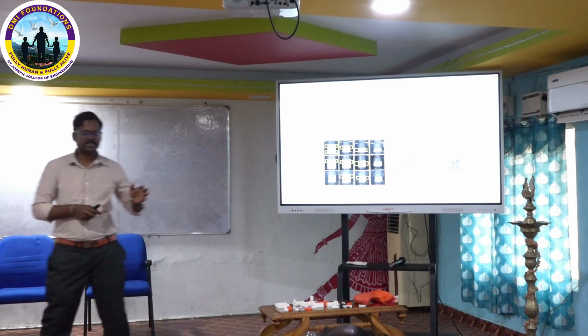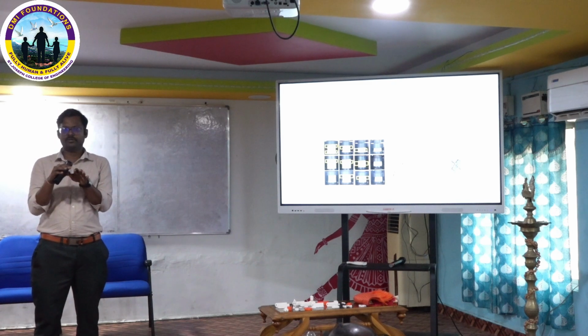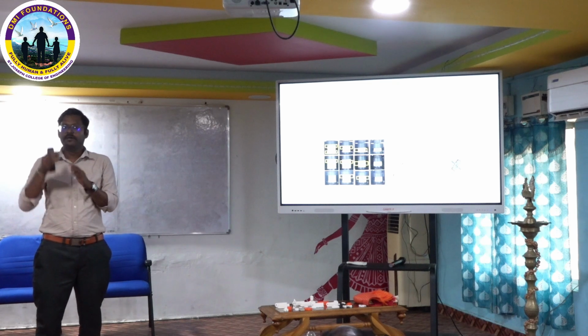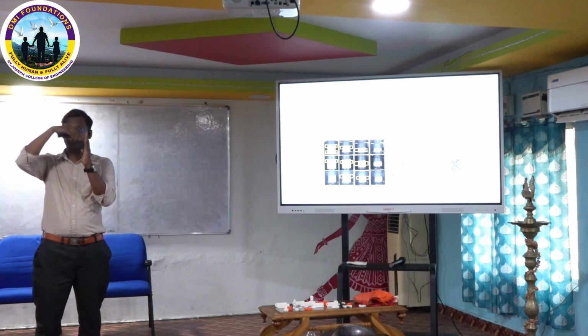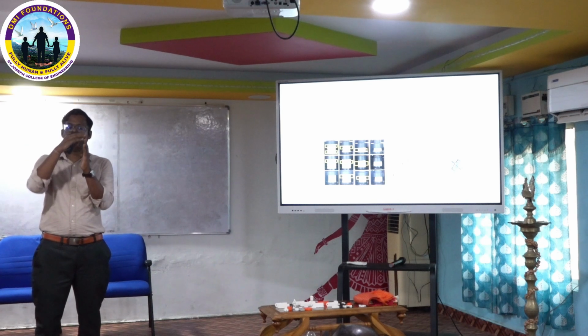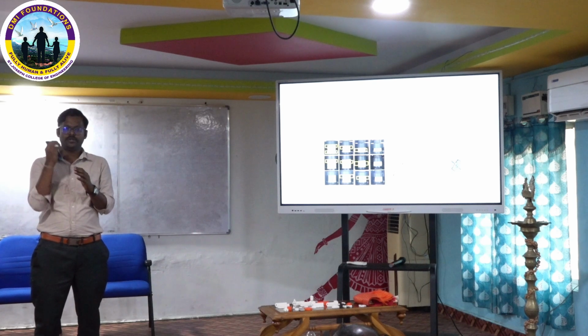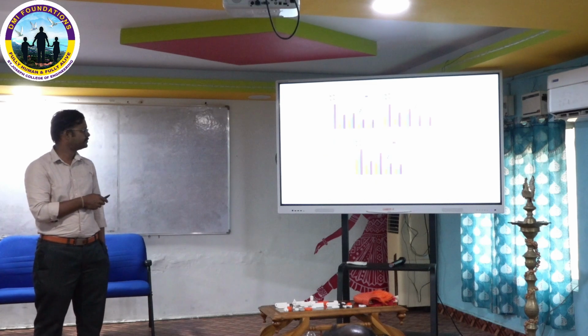So with this research study, what I conclude is that the maximum stability criterion is important to categorize the lattice structures or unit cells, but for modern designs it is not fully suitable. So we need to study the topology of the lattices with respect to the loading condition. If your strut is vertical, in the parallel direction of the loading, it will deform by buckling, so it will absorb more energy. Whenever bending happens, it absorbs minimum energy, initially absorbs minimum load and gets bent. So these are the observations we have made.